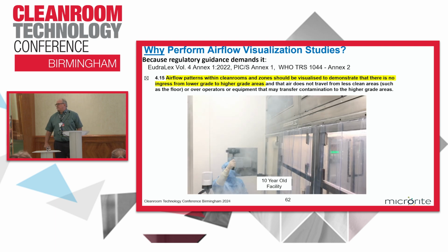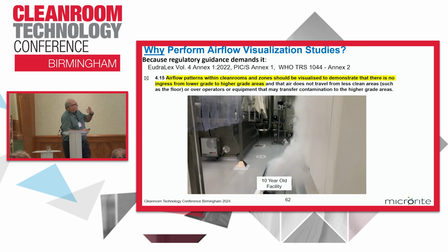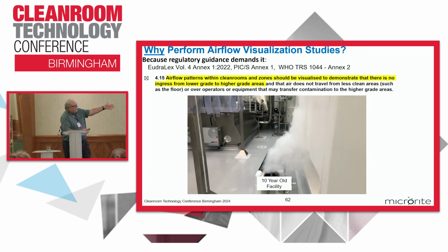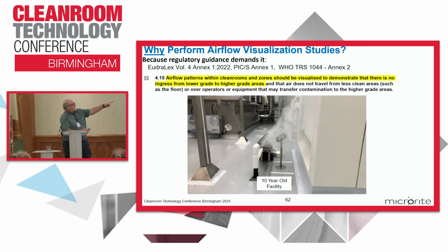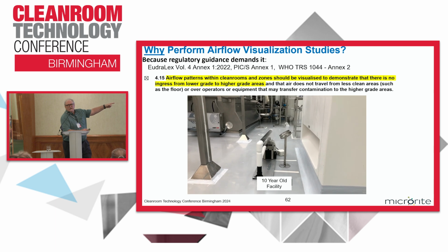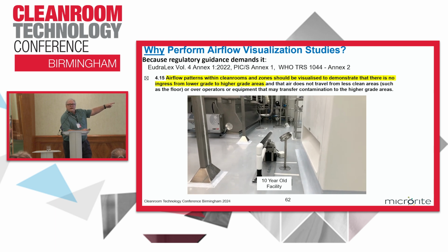Upwards movement of airflow. It was a bad design. The facility was in operation for over 10 years. They had intermittent contamination problems due to the bad design, and it kept qualifying. Again, someone would check the air return with an air velocity probe and then get a reading. But they didn't know how the actual air was moving.